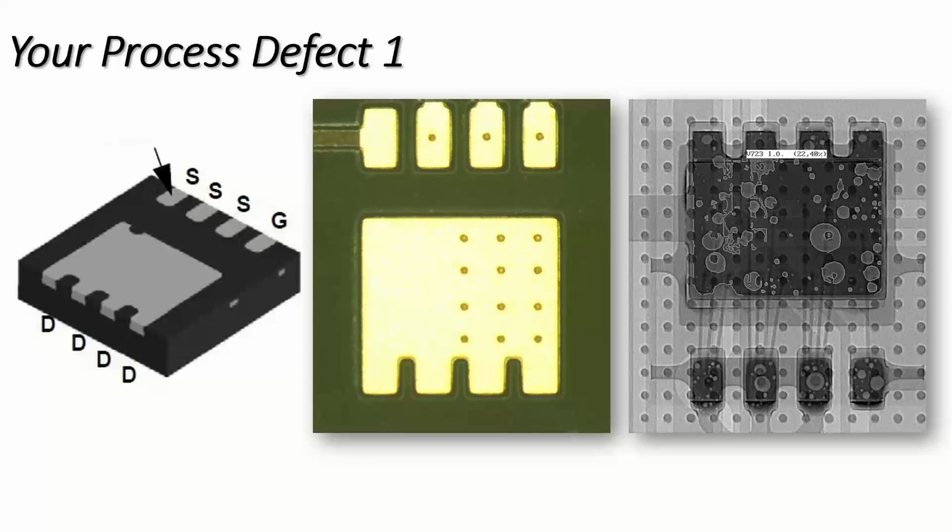What he's trying to do is reduce the amount of voids in his process or his package. He is not necessarily outside of any criteria that's generally discussed in the industry, i.e. a maximum of 25% voiding by surface area, but he and his customer would like to improve it.